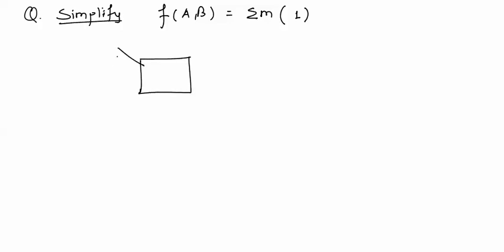We'll find the expression for f. We'll write the K map. In K map, we will draw a two variable K map, and this given expression represents that f, which is a function of ab, has its value logic 1 for the first combination, and we know that this block represents the zeroth combination, first combination, second combination and third combination.